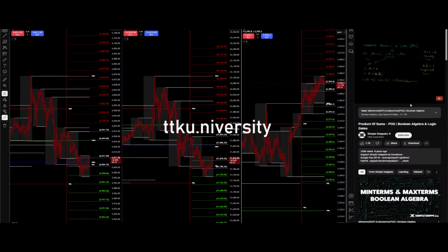Okay, so we converted this single variable term to a double variable term wherein we introduced the variable b, and this is a product of sum form. This entire thing is a product of sum form, which is a standard product of sum form since it consists of both the variables a and b. So the final answer to this entire question, I'll just write it over here, would be